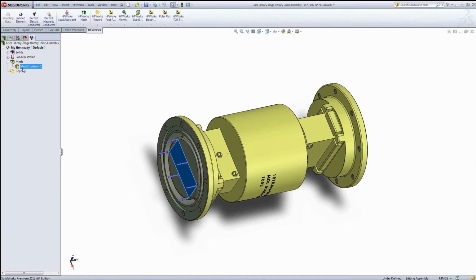It's automated. You can do the meshing this way, or you can do what we call adaptive meshing. The software can start with a default mesh, then compute the error and adapt the mesh adaptively. Adaptive meshing gives you assurance that the results have converged, but it will take longer because every time it has to mesh and refine the mesh until it arrives at convergence. Once you become knowledgeable with the software, you will know ahead of time which areas are critical, and you can mesh them fine from the beginning, and then you can get to results much, much faster.